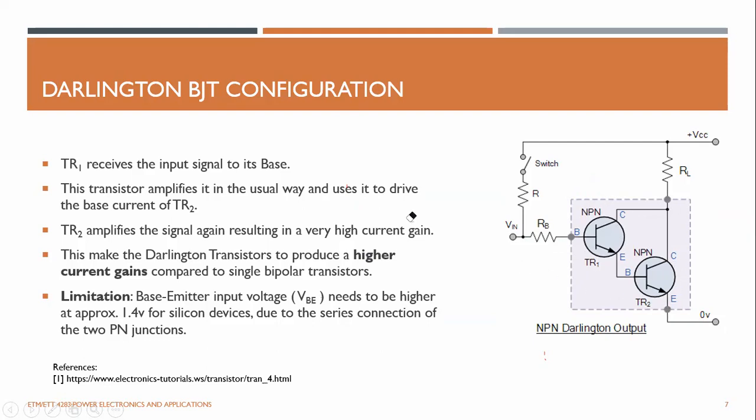So the operating principle is like this. This is the TR1 transistor, connected to a control signal via this R1 resistor, or this Vin. You provide a control signal, and that drives a small current through these two devices, base-emitter and base-emitter, because these two are connected in series.